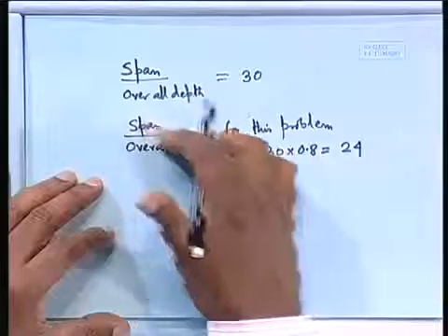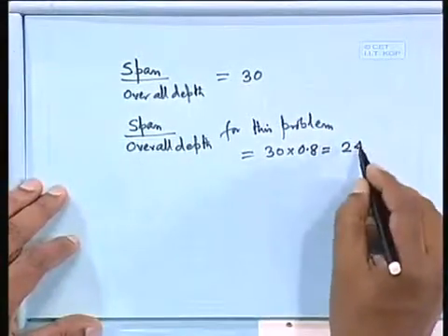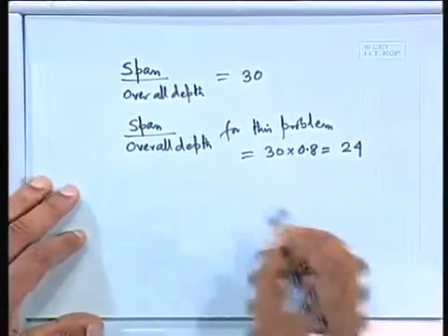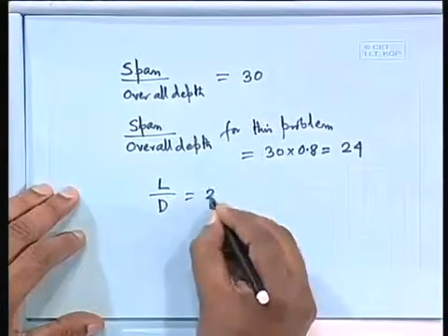It is not only a matter of bending; we also have to check it from the control of deflection point of view, and the span by depth ratio will help us keep it within the control of deflection. Span by 350 or span by 250 is the guideline for the overall deflection. So with this I can keep it within that limit. Here I am taking this 24, and it will be on the safer side. So I can write down L by D equal to 24.